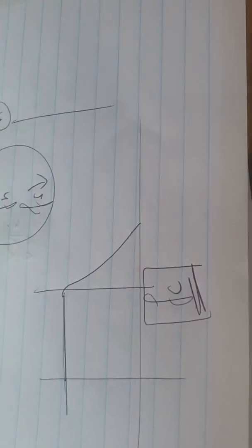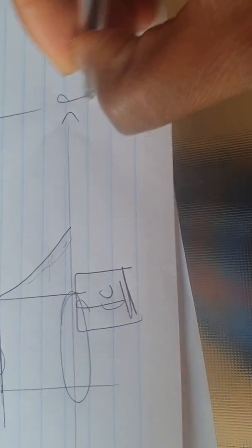So the circuit will have to have a significant gain, ideally of 1, because you want to pass the signal without changing its amplitude, but only the component of that signal that are below a certain frequency. And you're going to attenuate, meaning the gain on the other side will be very small, because we're talking about closed loop gain here with respect to frequency.